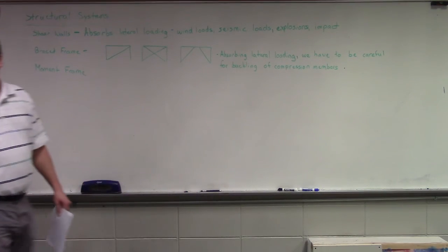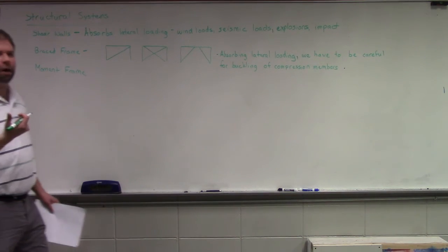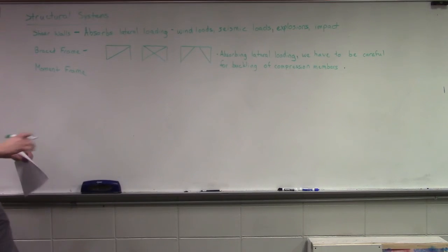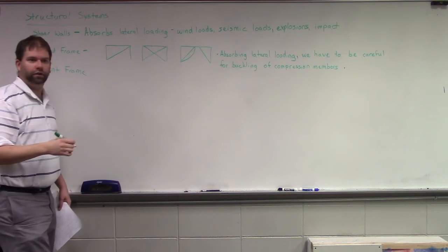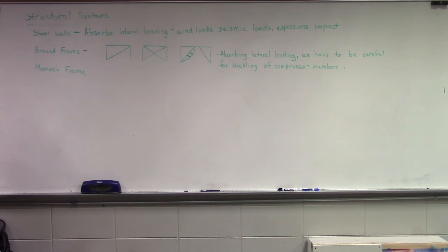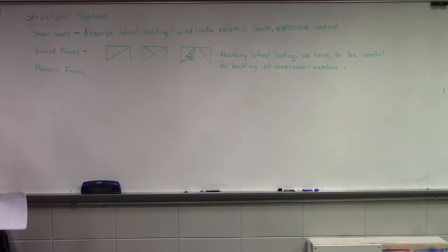Do you remember what buckling is? We haven't done really any homework problems with them, but I've had you read a couple little sections, one in the axial load, and then a portion of chapter 3 on shear and bending, which talks about buckling. What is buckling going to do to our cross bracing? It's going to blow them out. It's going to start deflecting like this, and get to a point where the material itself will actually fail, typically through some sort of shear, bending, or combination of shear and bending. So that's what we're interested in there.